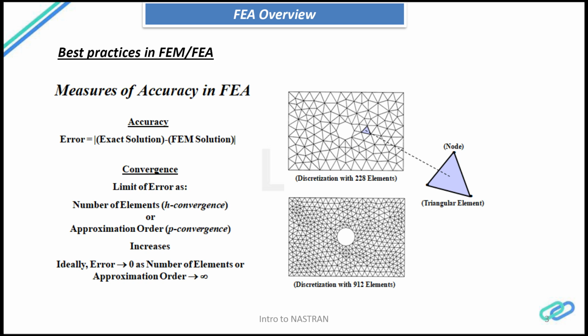Suppose I am handling a door assembly of a typical Airbus aircraft, my area of interest would be the maximum deflection at the center of the door. Imagine this is a square door: my area of interest would be the center portion where the maximum deflection would be, and the boundary where it is attached to the aircraft surround structure, the door surround structure. So there will be different areas of interest within the model.